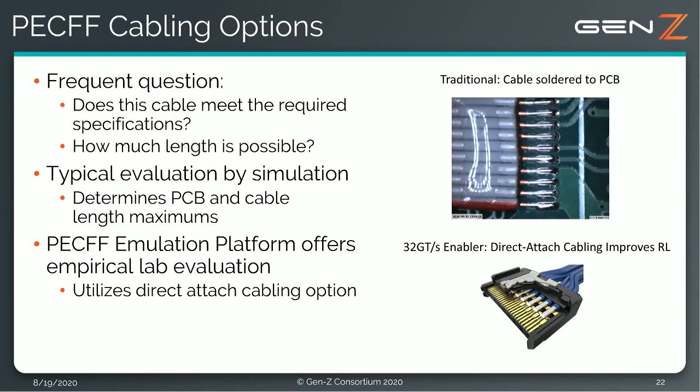Simulation is a tool. Also, the emulation platform here is a tool. So we can empirically discover in the lab what's the combination of board and cable length that's going to work with my PHY and give me an acceptable bit error rate.